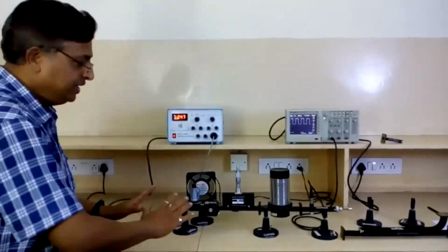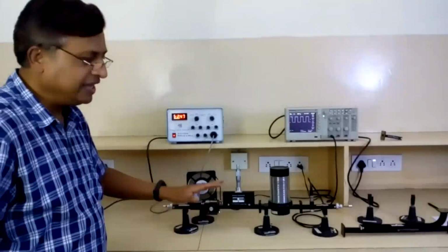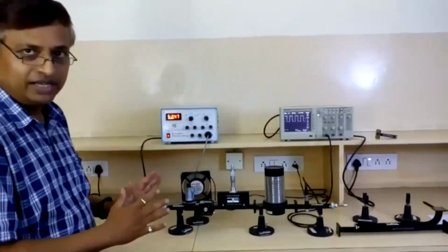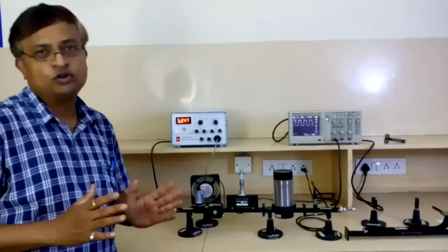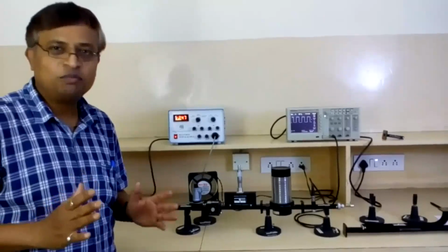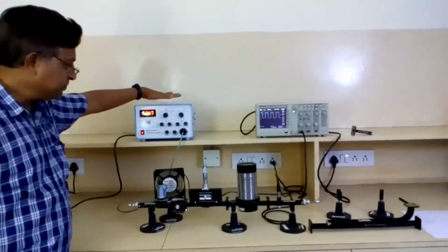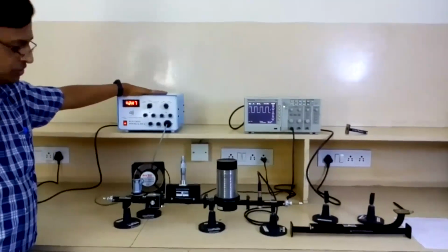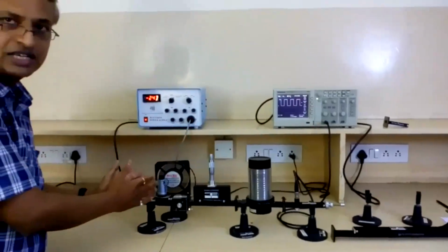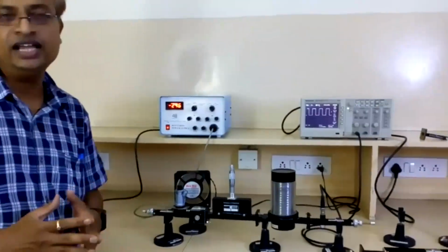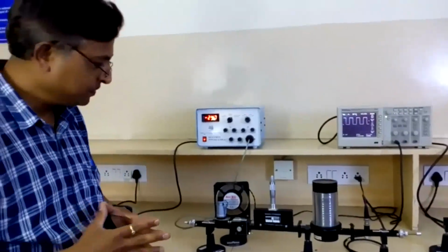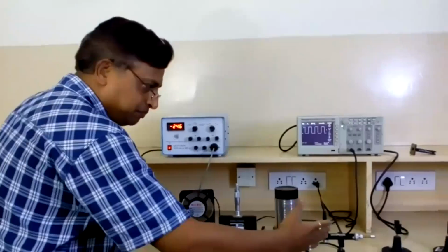Setup is already done over here using X band. So X band is 8.4 gigahertz to 12.2 gigahertz. This is the power supply which we use to drive the reflex klystron tube, which is generating X band frequency. The total setup is